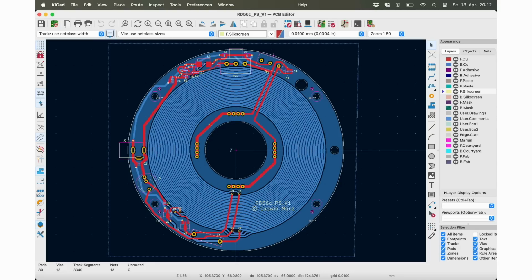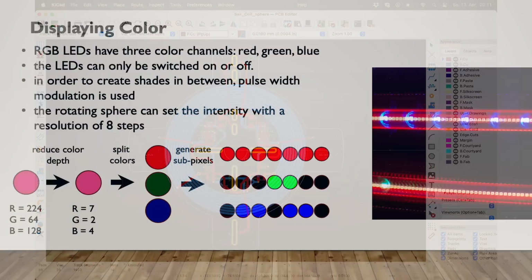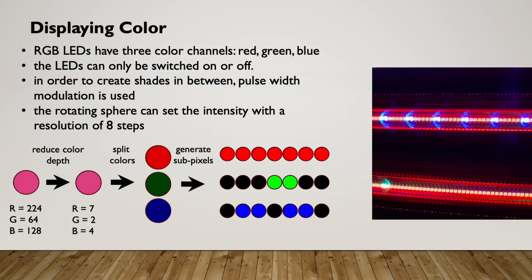is implemented as a printed circuit. The components are positioned around the edge of the board to avoid interference from the strong alternating electromagnetic field generated by the coil. The PCB with the receiver coil has several slotted holes into which both the LED board and the support board are soldered. The components in the center of the board are responsible for rectifying and stabilizing the voltage supplied to the LED board. Let's briefly talk about how the display is able to produce different colors.